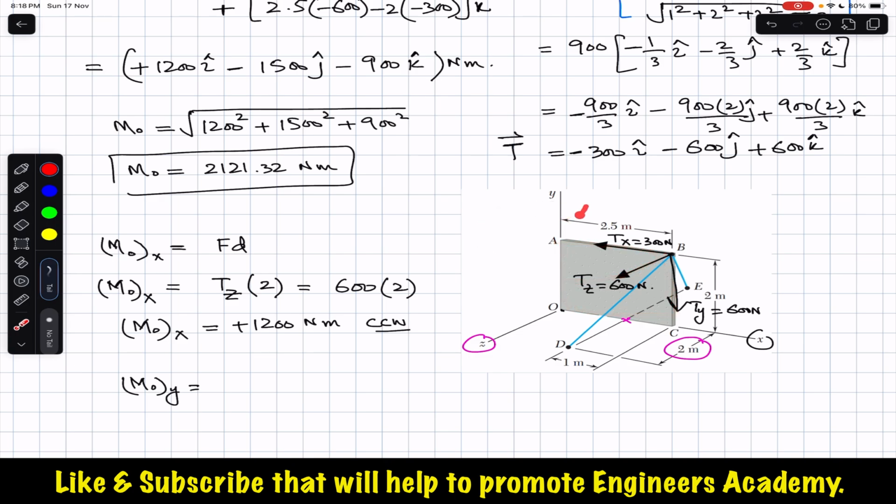And if we curl our right hand fingers in this direction, the thumb will point out in the y direction. So this means that this Tz, which has a magnitude of 600 Newton, is going to produce the counterclockwise moment about the y-axis. So for the counterclockwise moment, I will write minus, and Tz is again 600, and the perpendicular distance between the z component and the y-axis is this distance. This is 2.5. So we will multiply this with 2.5. And 2.5 into 600 is 1500, and minus Newton meter.